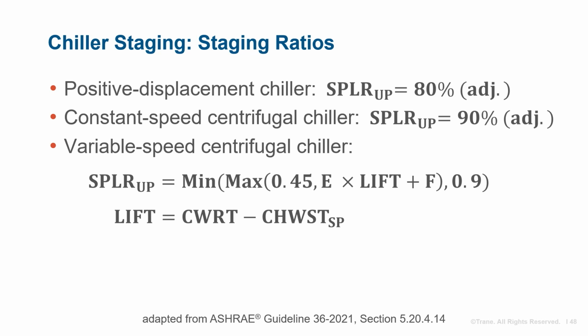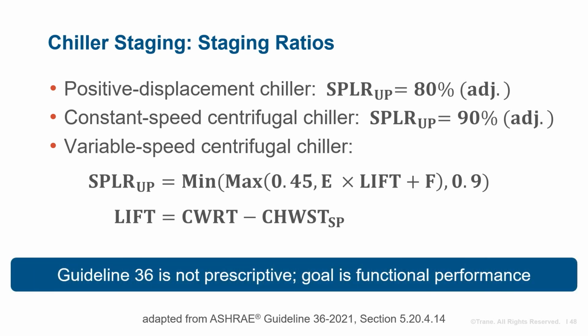Keep in mind, controls providers often have their own algorithms for staging chillers, which are often some variation of this methodology. Remember, these methods are a guideline, which is also why the staging part load ratios are adjustable. A designer may opt to not use these equations within their sequences, as the sequences are not prescriptive.